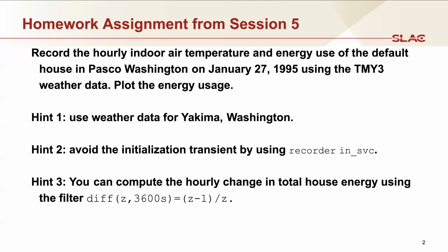Another important hint was the transfer function that's used to calculate a finite difference. When you look at the energy use in the house panel, it's an accumulated energy use. So what you see is the total energy use growing over time. And so if you want to collect the energy use for an hour interval, you have to set up a finite difference transfer function. And the definition of that transfer function is provided in this hint.